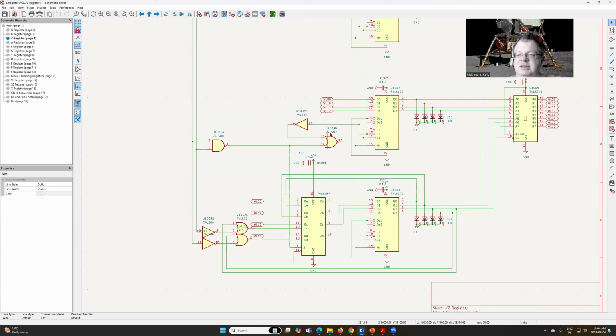We've said that if we're just loading it in normally because there is no Z15 or Z16, we've got an inverter and NOR gate that basically says just load it in, and we'll load these in right off the write line bus. If it is asserted, though, we won't touch any of these, but we do need to write either the 15 or the 16 into the D register. And so when we do this, there's a few things we have to worry about.